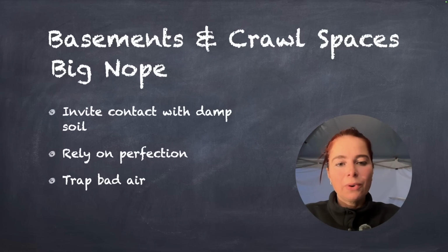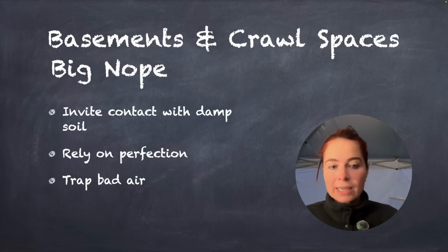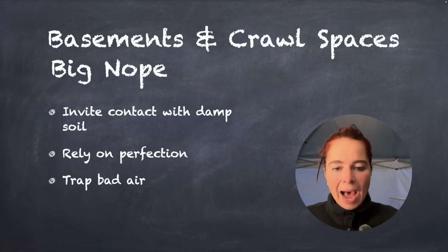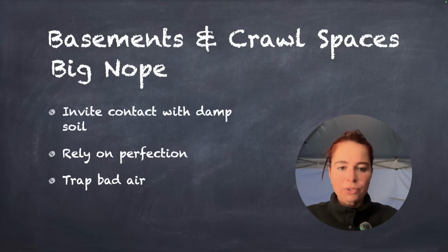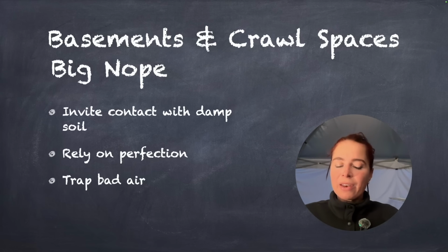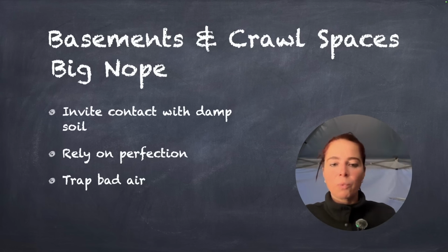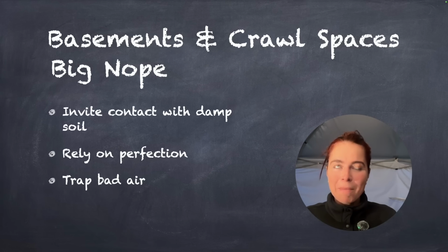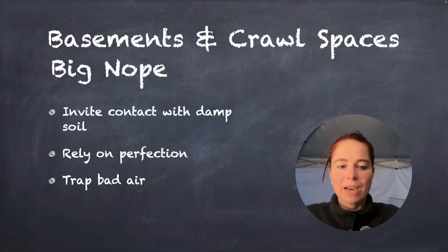So as you can tell, I'm not a big fan of basements and crawl spaces. They invite contact with damp soil. No matter how well you detail, water is always pressing on the walls. So in my experience and in my opinion, if you try to fight Mother Nature, she's gonna win. So let's work with Mother Nature is kind of my thinking. Let me know if you think the same in the comments. Love to have a discussion about that.